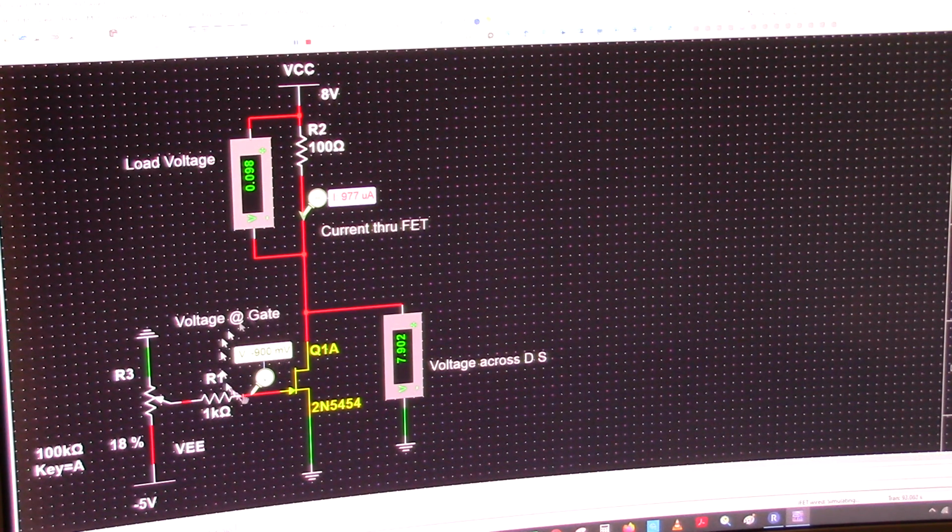So you notice this is increasing. Actually I said negative 1 volt. So it's negative 1 volt, and you notice that the transistor is almost shut off. It's 810 microamps, so 0.8 milliamps. So 3 milliamps to 0.8. So I'll keep increasing.